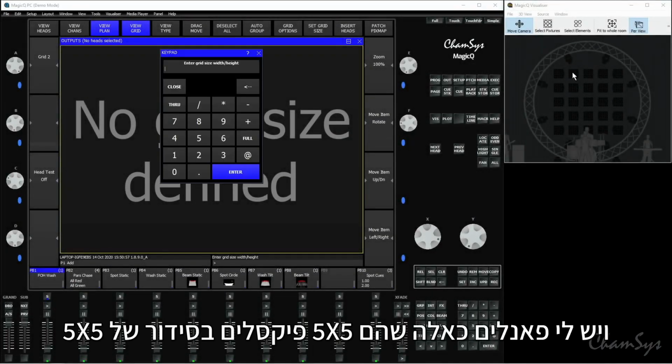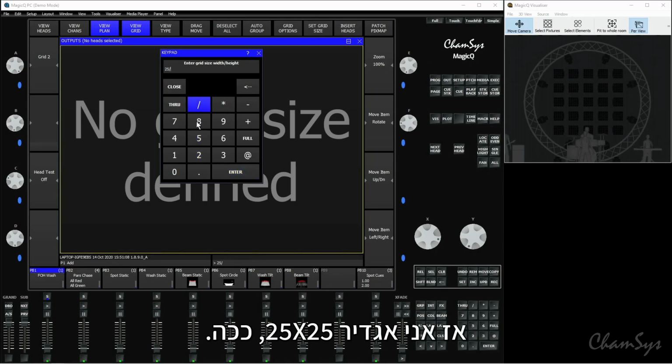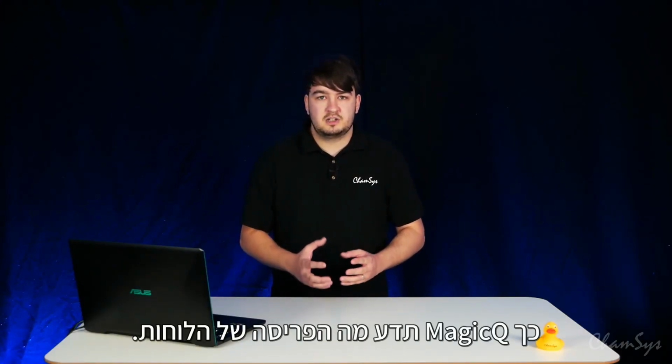And I've got these panels, which are 5 by 5 pixels in a 5 by 5 array. So that's a total of 25 by 25 pixels. So I need to set 25 by 25, like so. So now that we've got our 25 by 25 grid, we need to insert those panels into that grid so that MagicQ knows how those panels are laid out.